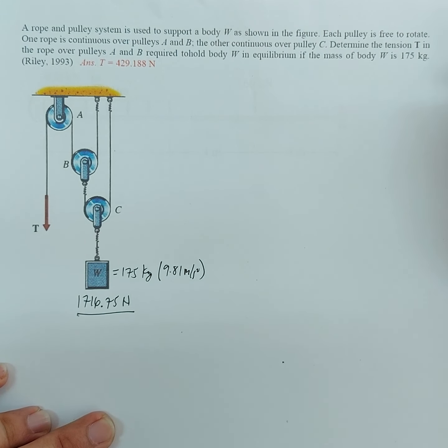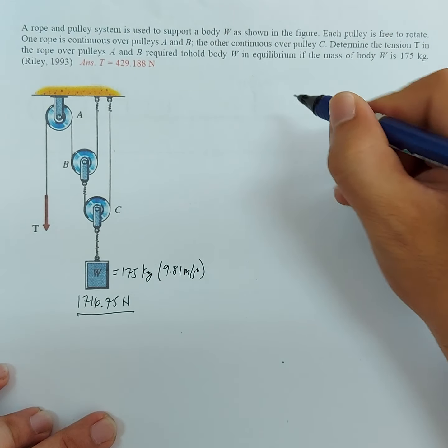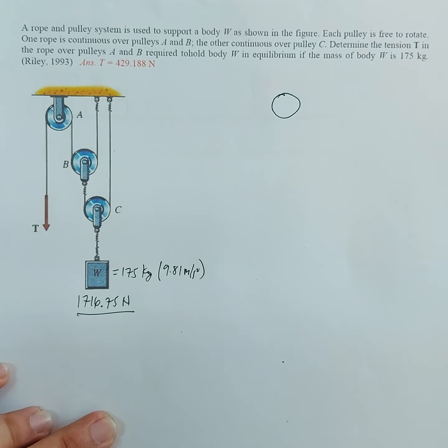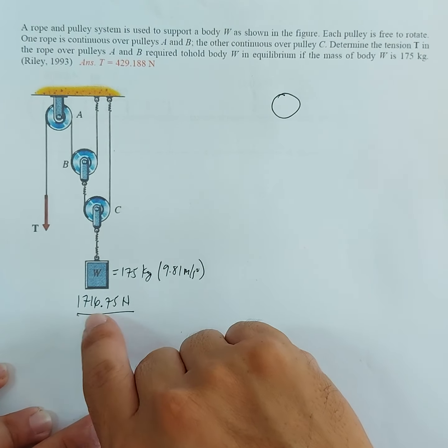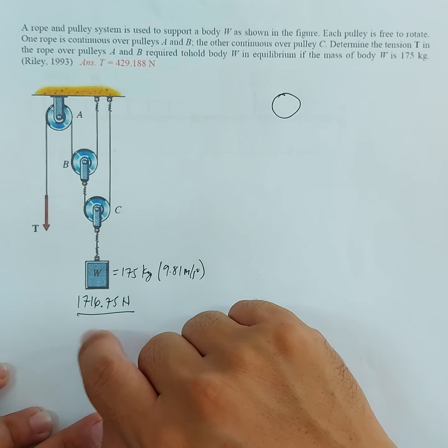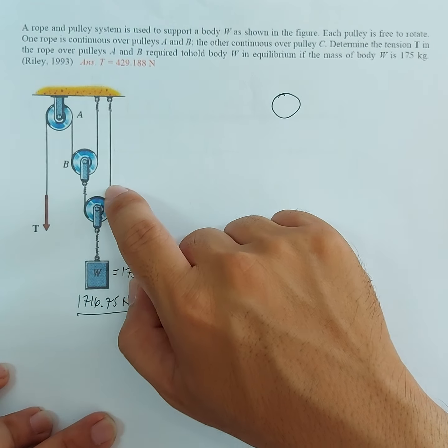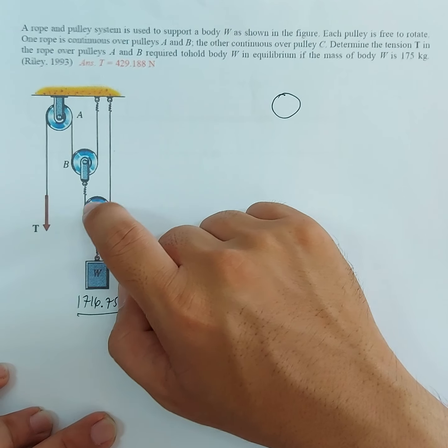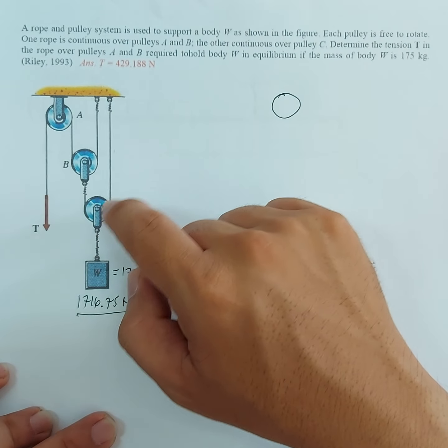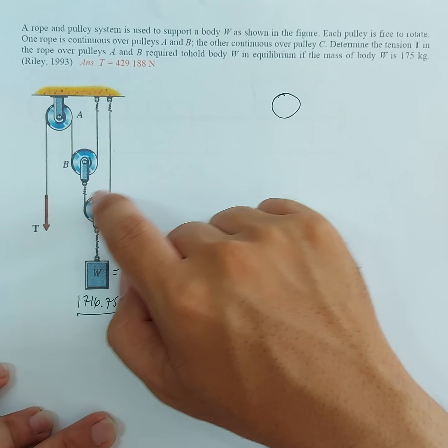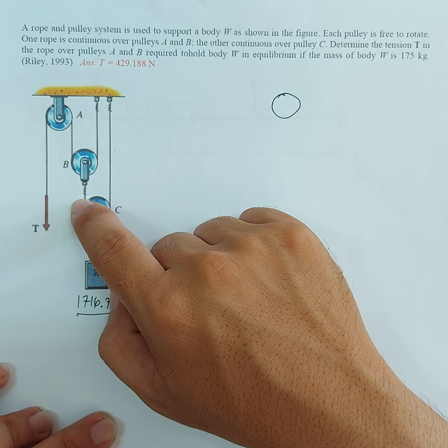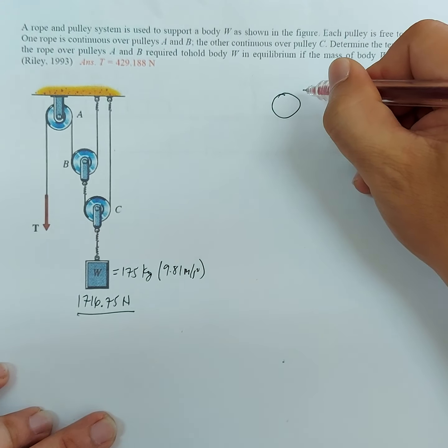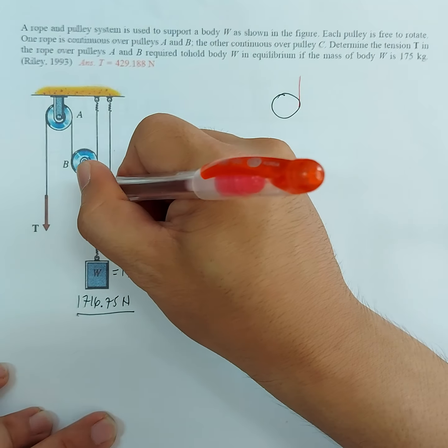So let's start at pulley C here. So pulley C. At pulley C, let's draw the free body diagram. Kasi nandun yung known na weight eh. Doon tayo mag-start kasi alam natin yun. We can solve for the tension dito. And then if we are now able to solve for the tension at this rope, so may rope C, alam na natin ito. So we can cut that. And then now solve for T using equilibrium conditions.